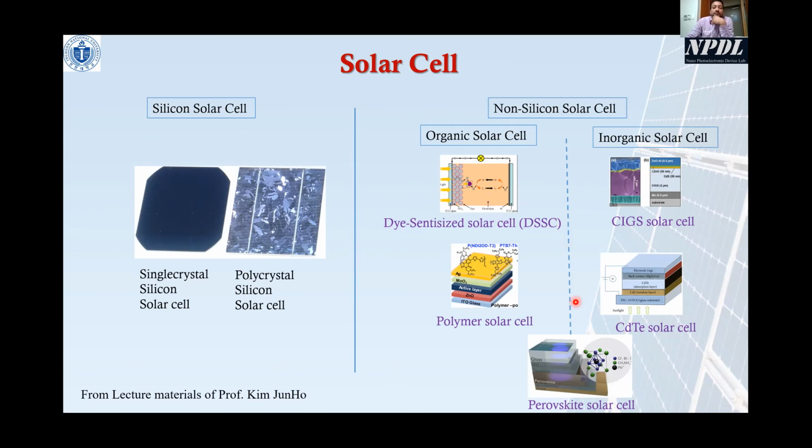And if you consider high efficiency, the perovskite solar cell is the world's highest efficiency solar cell. But one problem is it degrades too quickly in the air, because in the perovskite solar cell there is a hydrophilic or hydrophobic layer that is also affected by the humidity. So that is the main concern of the perovskite solar cell. If the humidity or stability issue can be solved, then the perovskite solar cell can be the world's leading renewable energy resource compared with other sources, because perovskite solar cells almost cross 30% efficiency, but the limitation is it is not stable in air and it's affected by the humidity.